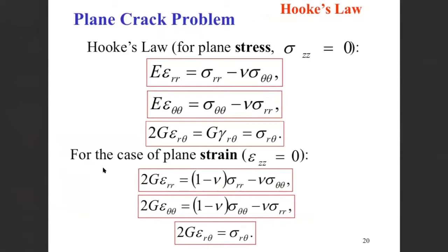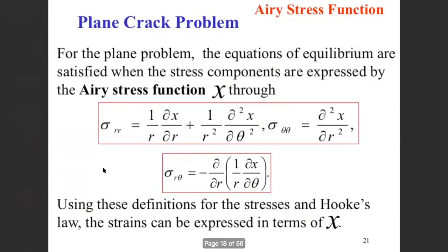For plane strain, we can think of a very thin sheet out of an infinitely large block, where we have no strain in the zz direction, but we do have a stress because we're confined by the other material. And this is just Hooke's law. It just looks weird because instead of writing it in matrix form, we're writing it in regular form, and it's in polar coordinates.